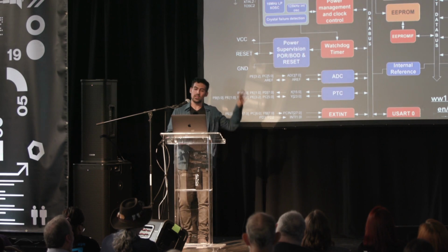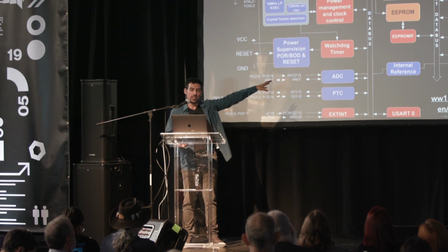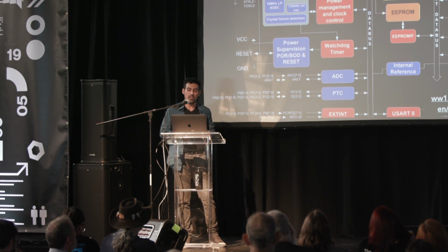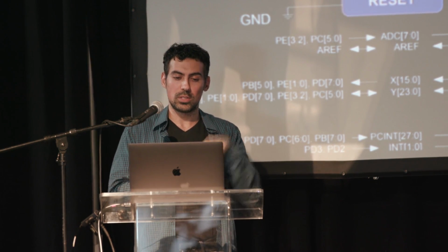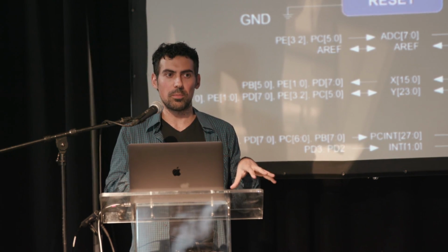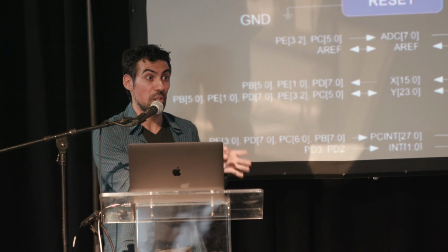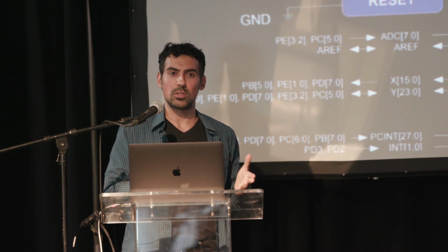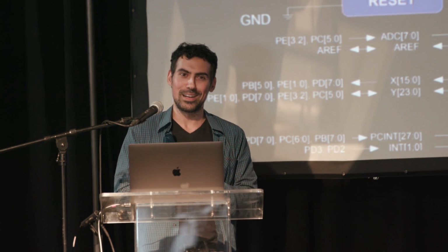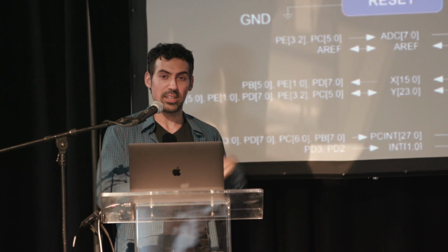Except for the fact that in your, say, Uno or your ATmega, you have all of these different blocks, right? You have your UARTs, your SPI, your RAM, your CPU, your ALU. All these different pieces are taking transistor space, or silicon, that you can then replace with something else. Maybe you wanted to generate rainbow tables instead of having SRAM.